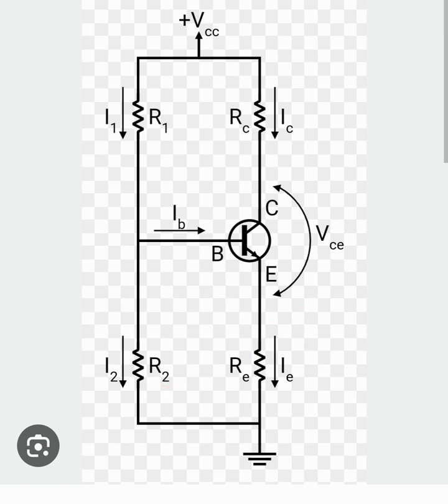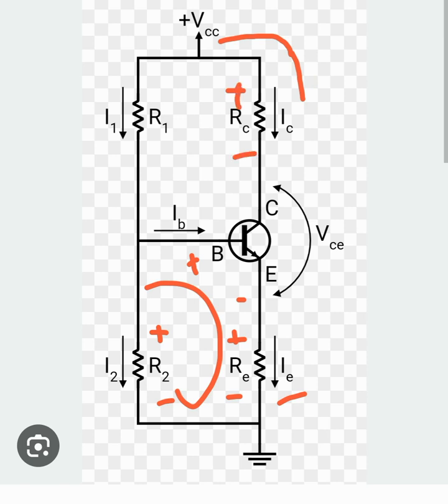That voltage is applied and you have this VBE right here, and then there is a current IE, the emitter current, that flows through this RE, and therefore that's the loop. You can apply KVL in this loop to know the voltages and the currents. Similarly, for the outer circuit of the BJT, you can apply KVL in the outer loop, which is VCC minus ICRC, that is the collector current that flows through RC, minus VCE, this drop, minus IERE, and equate it to 0. So there are two loops that you can apply.